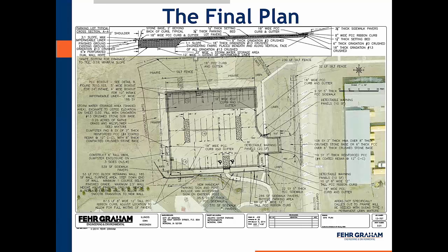So knowing that, knowing we didn't have sandy soils that infiltrated real well, we designed a deeper reservoir at the lower end. You can see that at the left-hand side. That's 5 to 6 feet deep, and that was sized to hold close to the 100-year storm for this area with zero discharge or zero infiltration. So we've got a lot of storage volume there. Anything that hits this parking lot is going to drain through the pavers and get down into that lower storage area.